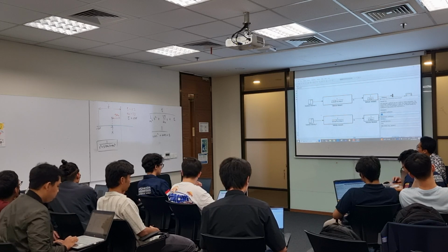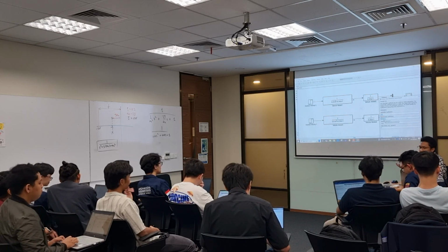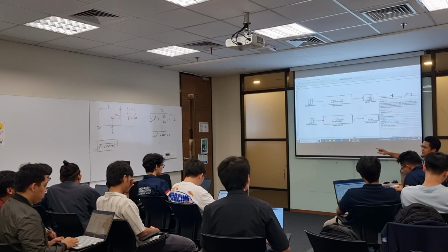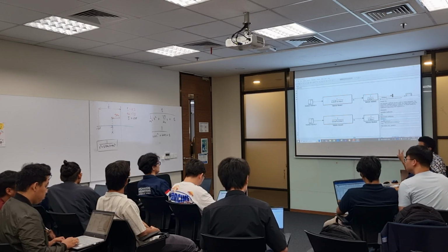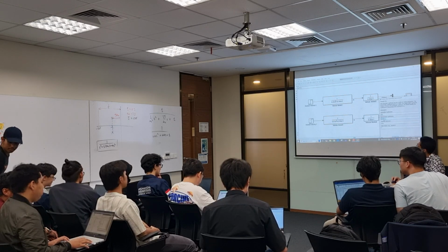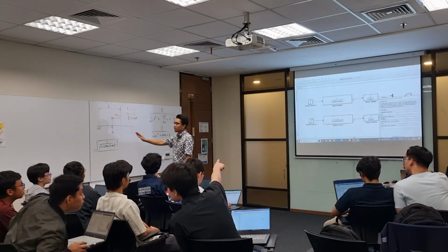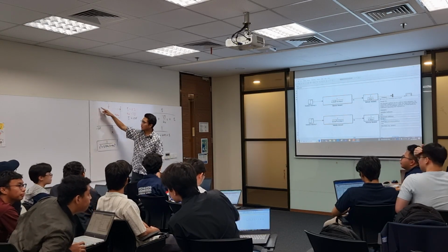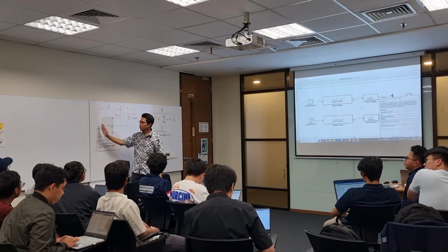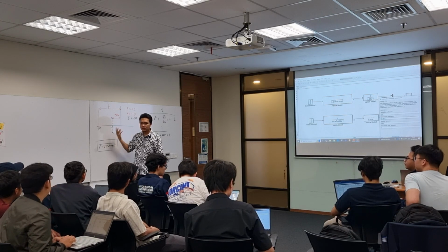You increase the tau so that the first order system pulse moves to the right side. So we want to simulate the two systems. The first system has 1/tau to be 20. The second system, we want to move the 1/tau to the right side and see what's the effect.